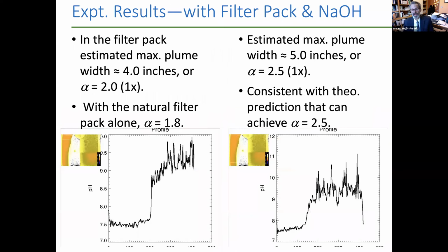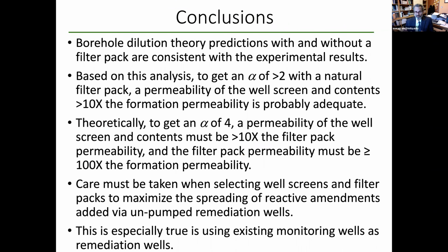And then when we go downstream and we look at the plume in profile where we're into the sand aquifer, we're getting a plume width of about 5 inches, or an alpha of 2.5, which is very consistent with our theory and our blue dye experiments. So based on these results, we believe that the borehole dilution theory gives good predictions of the plume width emanating from the well with and without a filter pack, very consistent with our experimental results.